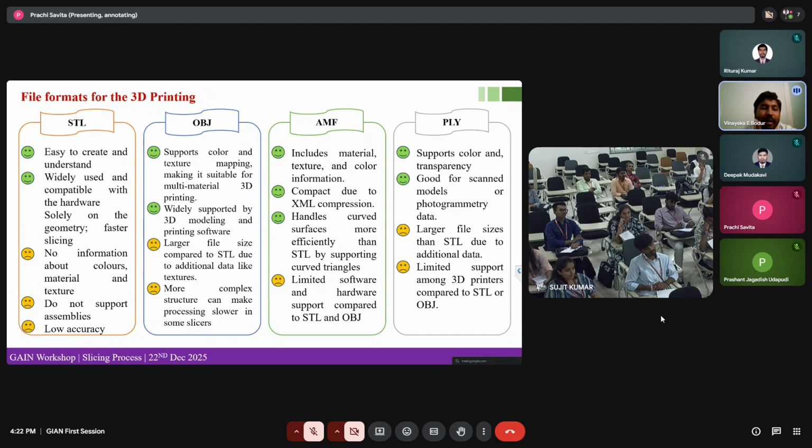The geometric flexibility of OBJ is a significant distinction. There is a significant distinction between OBJ and STL, and it lies in the types of polygon supported. While STL is strictly limited to triangles, OBJ files can store quadrilaterals, hexagons, and other complex polygons, as well as freeform curves and surfaces. This geometric flexibility allows for a more efficient representation of certain shapes, often providing higher accuracy with fewer elements.